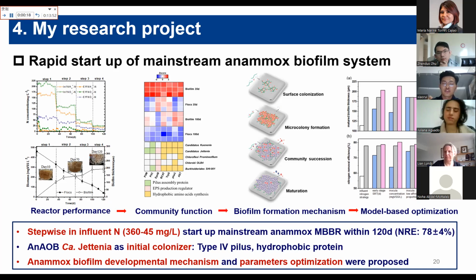Nowadays it's the shortest time to start up a mainstream Anammox MBBR, and we found the most important species that can help to promote biofilm formation. Moreover, we discovered the biofilm development mechanism, and we constructed a biofilm development model to guide the parameter optimization